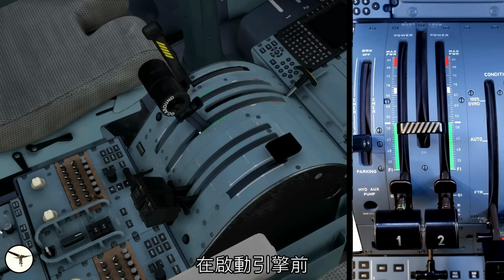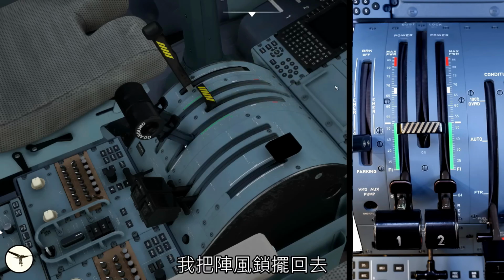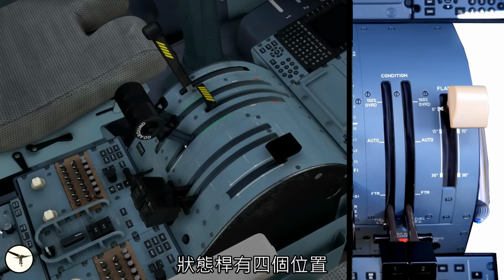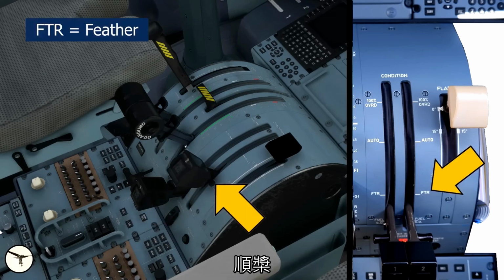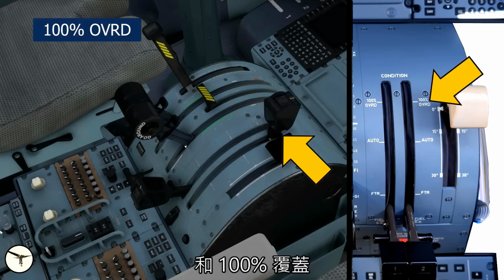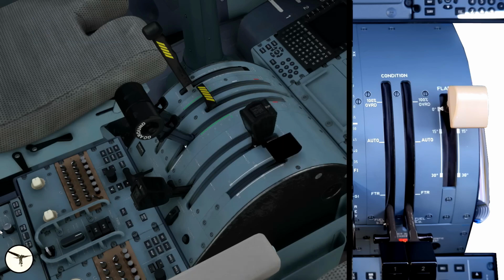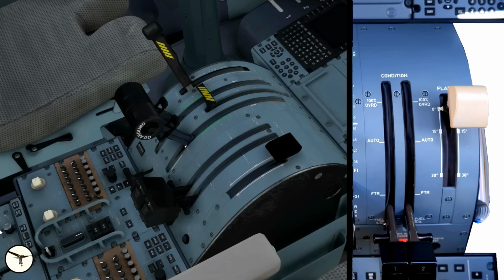Before starting the engines, the power levers are set in ground idle, and we put the gust lock back on. The condition levers have 4 positions: fuel shut off, feather, which is the position used for engine start, auto, which is used for flight, and 100% override, which is used in some situations. Before start, the condition levers must be in fuel shut off.